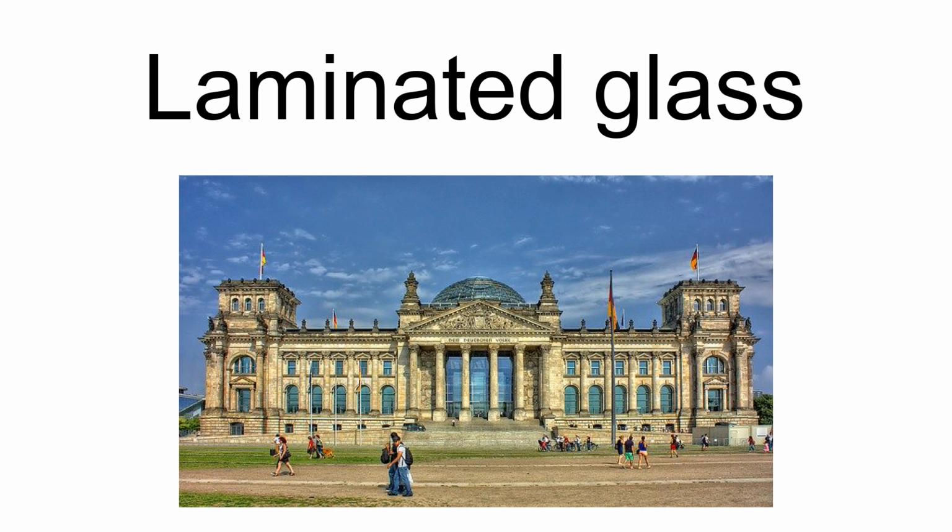There are several types of laminated glasses manufactured using different types of glass and interlayers, which produce different results when broken. Laminated glass that is made up of annealed glass is normally used when safety is a concern, but tempering is not an option. Windshields are typically laminated glasses. When broken, the PVB layer prevents the glass from breaking apart, creating a spider web cracking pattern.